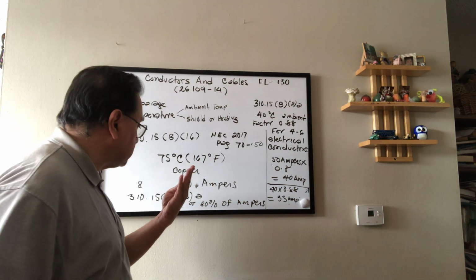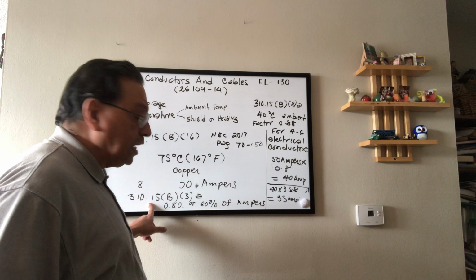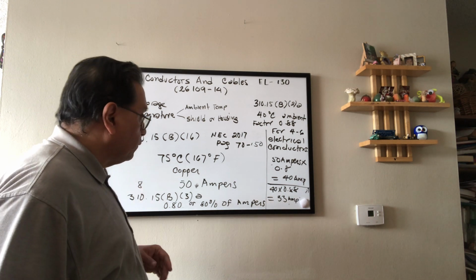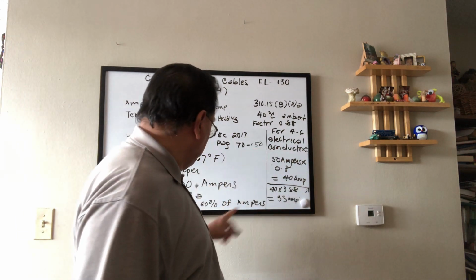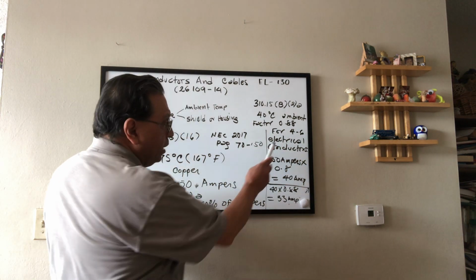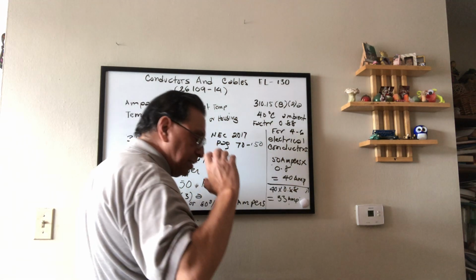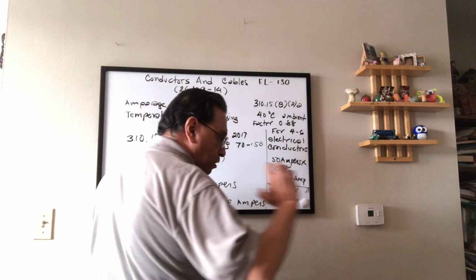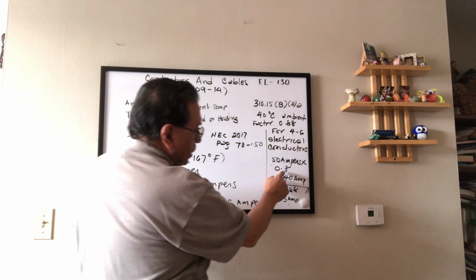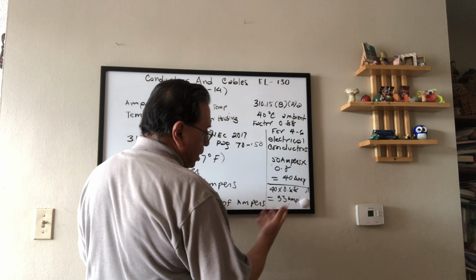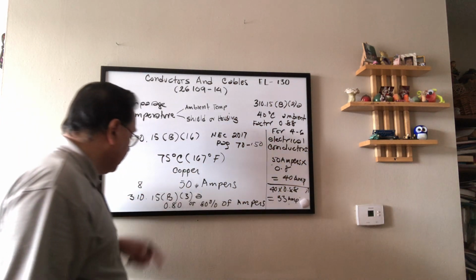Then we need to adjust the 50, and we use the second table that is telling me, depending on the number of conductors, from 4 to 6, okay, you will have between 4 and 6 electrical conductors on the same pipe, on the same conduit. Then you need to multiply this amperage times 0.8, reduce it to 80%, which is 40 amperes.